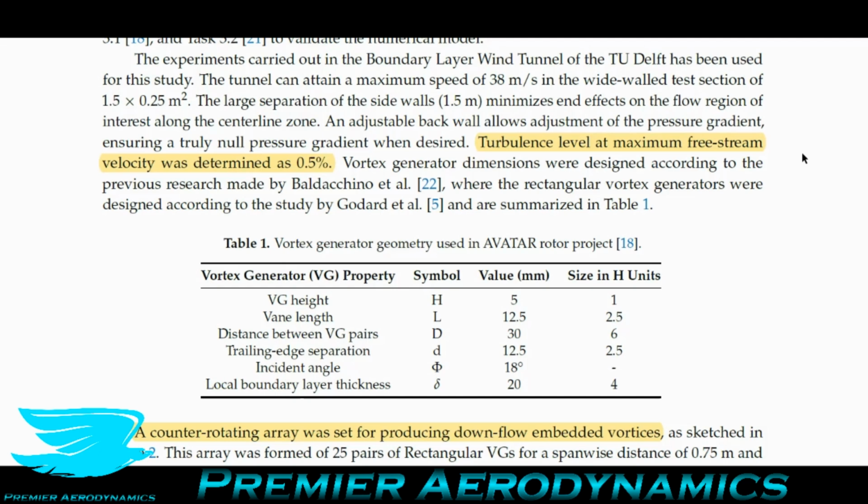And that means that at, I would say, about a Reynolds number of 300,000 to 500,000, you're going to start to get transitional flow, maybe 200,000. Below that, you have approximately laminar flow. Above that will be turbulent. That's what a turbulence intensity level of 0.5% will yield for a typical flat plate.